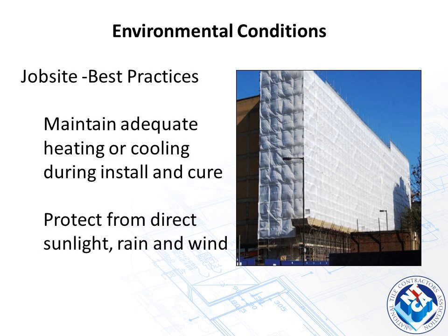Certainly a best practice is to maintain heating or cooling during installation and cure, regardless of which is needed. You'll also notice that this large tent also has ventilation, which is critically important. Tenting is not something that we're used to in the tile industry, but all the other facade industries are. You look at installers installing stucco or eaves or exterior claddings in environmental conditions, again in cooler weather, or for that matter, driving heat. They're going to cover up those walls because they want to maintain as consistent a temperature as possible so that they don't get inadequate drying or inconsistent drying for that matter.